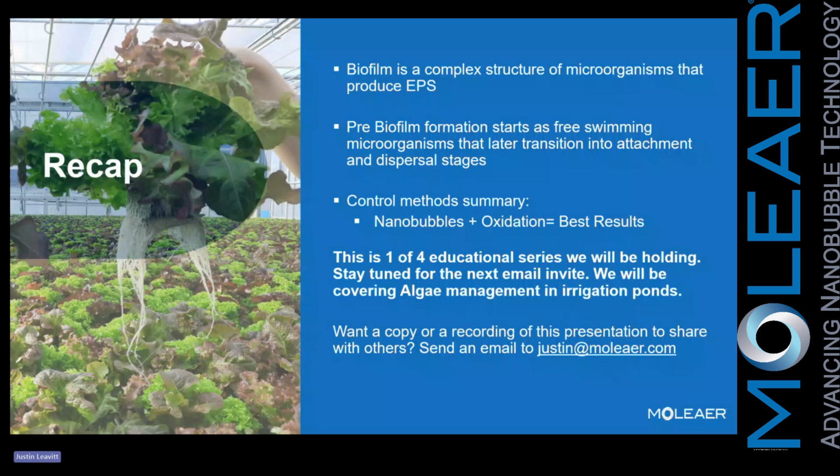So to quickly recap, because I'm a little bit over on time already, biofilm is a complex structure of microorganisms that produce EPS. That EPS is what makes them so difficult to manage. One, because it can continuously spread throughout your system, but also it protects them from the typical mode of action that we are utilizing, which is oxidation.